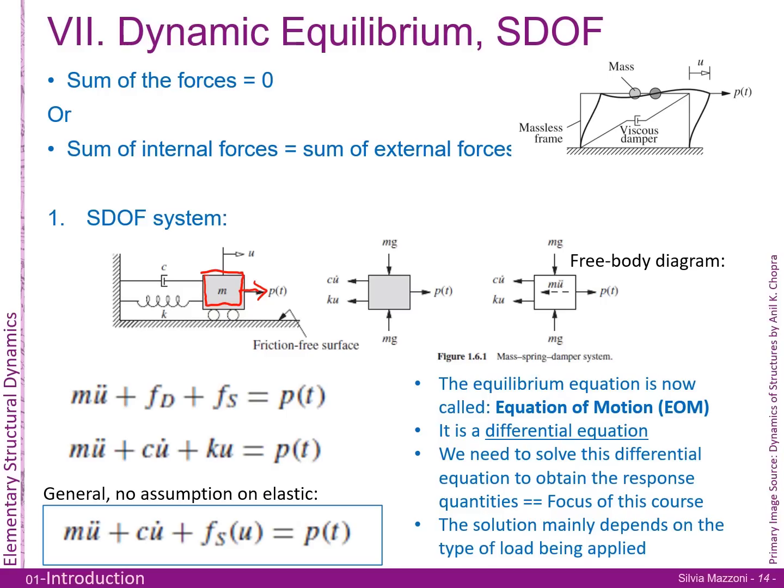Then there's always two types of free body diagrams. There's the one here that shows the object, but then you have to remember to bring in the inertial force as well. See, here's gravity, but gravity cancels out, so we don't worry about it, and we're really interested in this degree of freedom. Okay, we do have inertia in the other direction, but it's reacted by the wheels and the supports here. So we don't have to worry about the inertia in the vertical direction for this case. And so this is degree of freedom 1, a simple single degree of freedom.